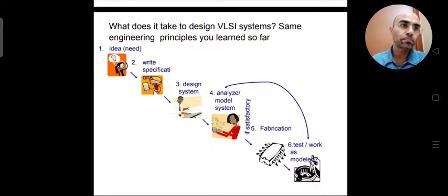So you want to program it. Automatic, to clean the houses you want the mopping device. So this is the basic idea. For this you will find that my machine should be of this much area, it should be battery operated, it should work at this much power, and it should operate for this many hours. And it should be able to automatically differentiate between the walls and the furniture which is kept there, so it should not collide with that furniture or the walls. Like this you come up with certain specifications.